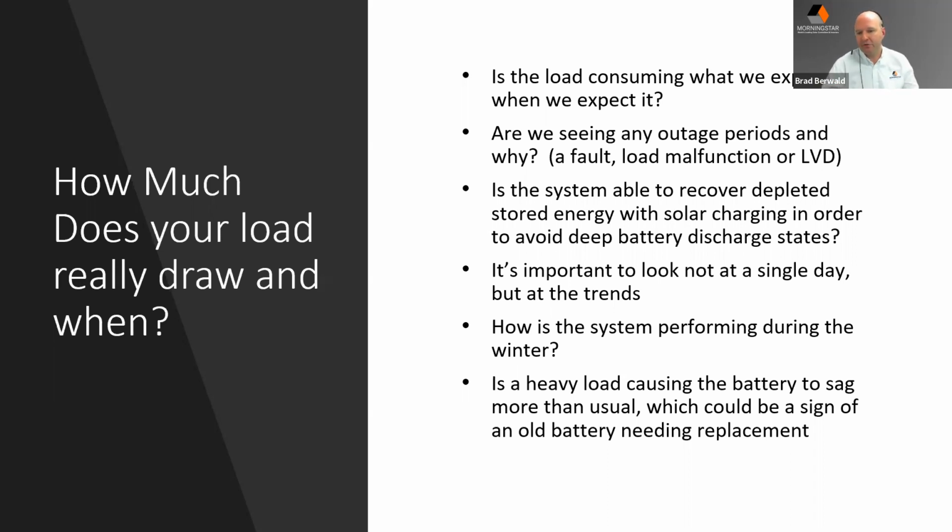Is the system able to recover that depleted energy with solar charging in order to keep the battery out of those deep discharge states? You want to be hitting absorption, ideally at the very least every, I'd say, 10 days. More often, like within the week, is really much better and much healthier if you want to see that kind of lifetime, especially out of lead acid. In the case of lithium, it's not hurt by partial state of charge much, but it's something you want to take into account.